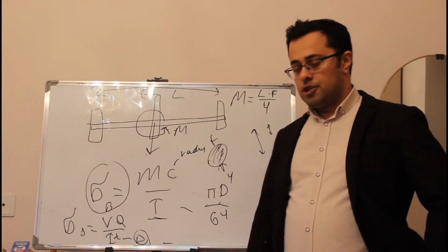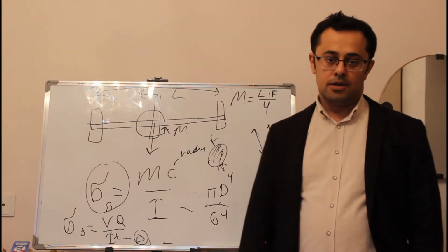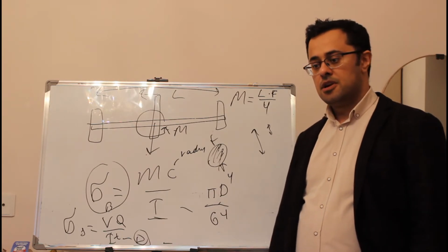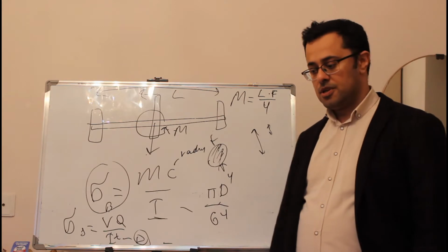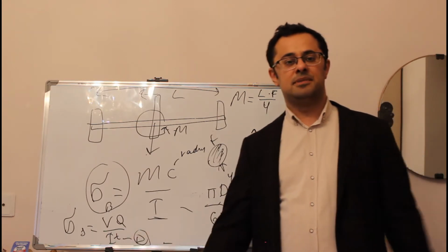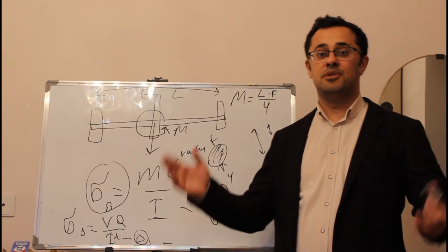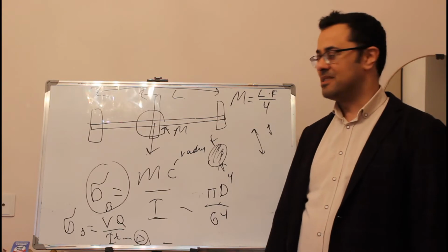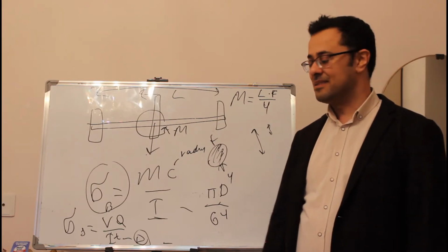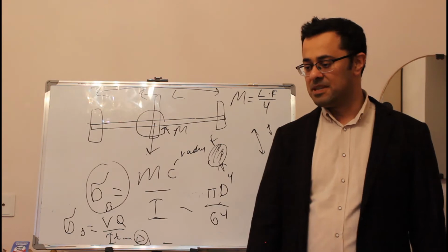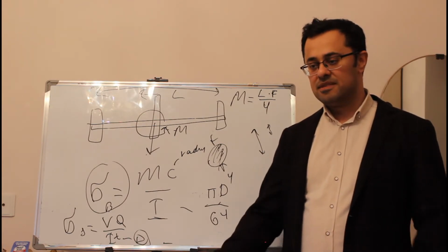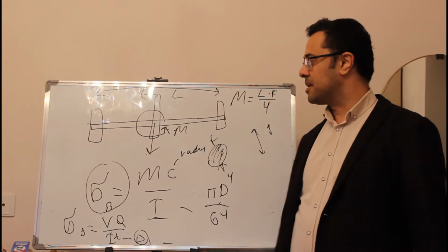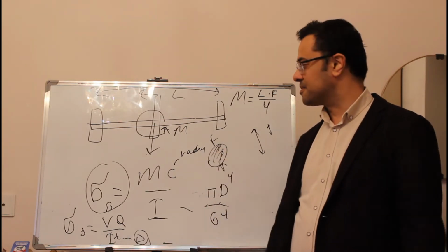You calculated shear, you calculated bending. There are other stresses like tension, like compression, like torsion. Torsion is not happening because it's rotating easily. Torsion will happen only when the bearings get total damage to the system, but not today. So bending, torsion, buckling or not buckling. I don't see any buckling here because there is no force.